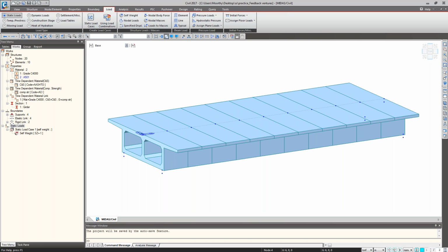This is the example we have practiced in session 1. This is a two-cell straight box girder which contains only the self weight, and we have provided two bearings on either side. In this session we will complete the other loading part, that is the superimposed dead load or bearing surface and pre-stress load, plus the construction stage analysis simulations.